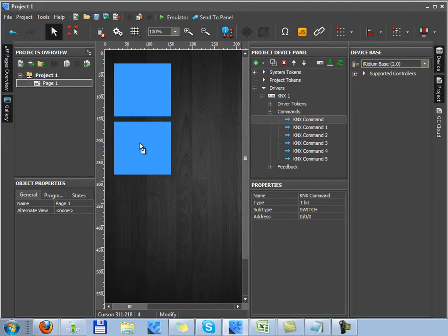a dialog window opens. It includes different types of command assigning, for example, send string, sending a string in the ASCII format, send number, sending of the decimal value of the variable, send token, sending the value defined by the graphic item. Send token is always used while working with levels, trigger buttons, up-down buttons. I told you about them in the previous lessons.